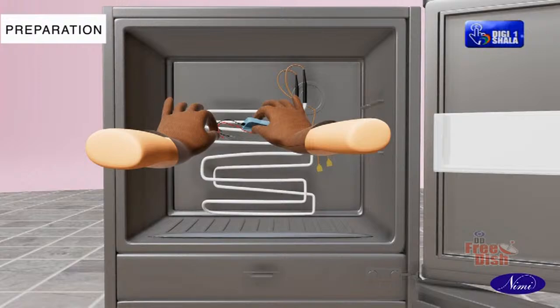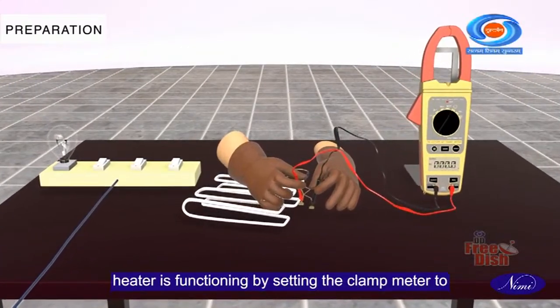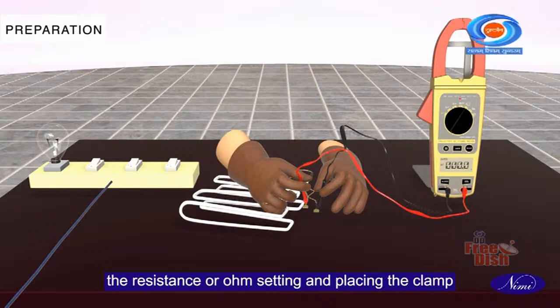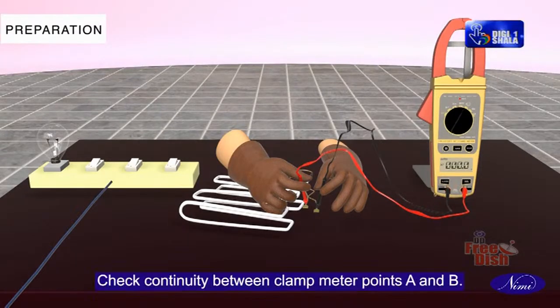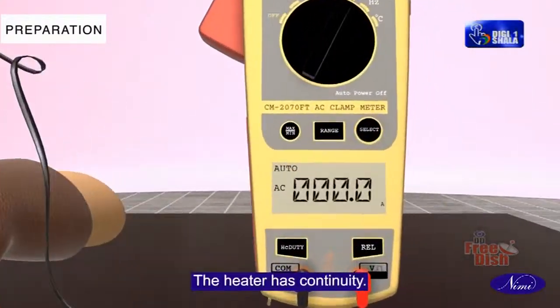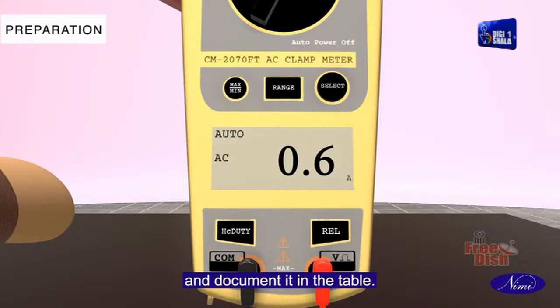Replace if needed. Perform a continuity test to check if the defrost heater is functioning by setting the clamp meter to the resistance or ohm setting and placing the clamp meter probes on each end of the heater element. Check continuity between clamp meter points A and B. The heater has continuity. Measure the resistance of the heater and document it in the table.